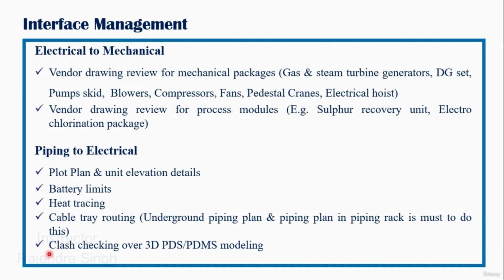And definitely clash checking, hard and soft clash checking over the PDMS modeling. Often we have to walk through the 3D model in Navisworks and look out for any clashes or any issues whenever the modeling is happening, so as to amicably align with respect to the space for the 3D modeling of electrical and piping discipline.